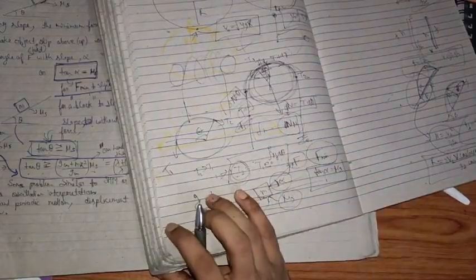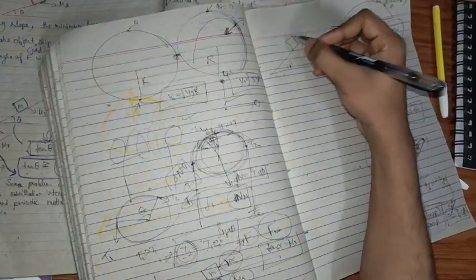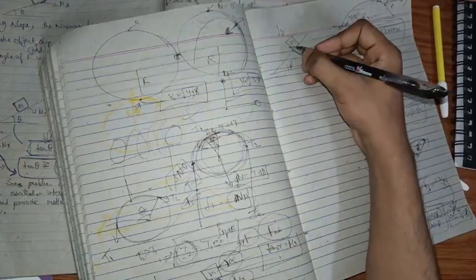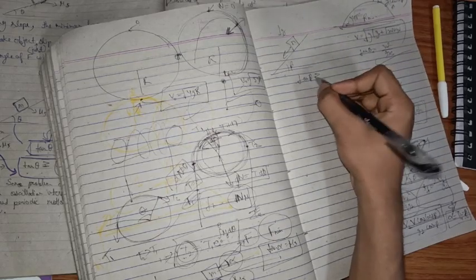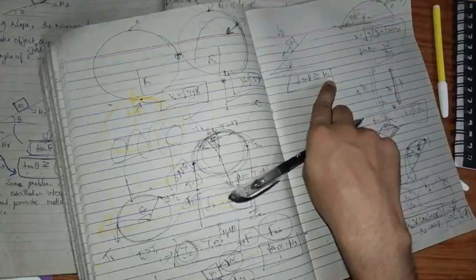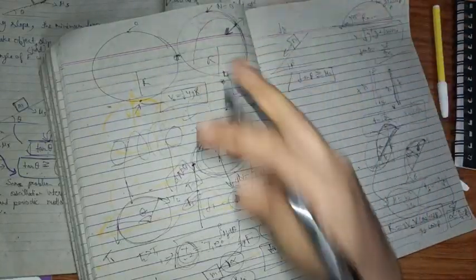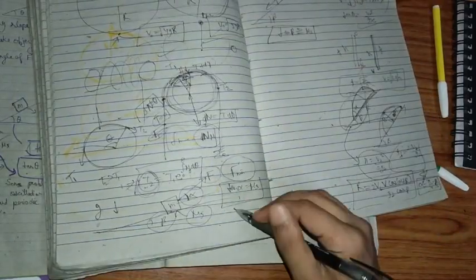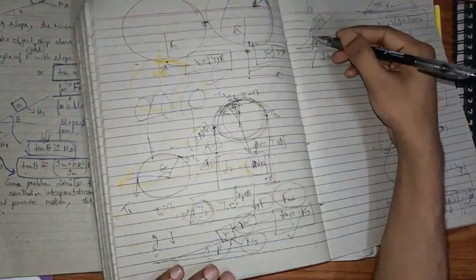And there is another case in which we have a slope at angle beta, and on this slope we have a mass m, with gravity acting. In this case, if the slope is changed, the mass will start slipping when tan beta is greater than or equal to mu s. It means it will slip when tan beta is equal to mu s or greater. Slipping will only occur after you cross this value of beta, while in the other case the minimum force occurs at this angle.